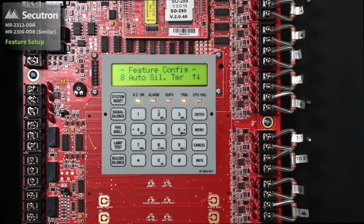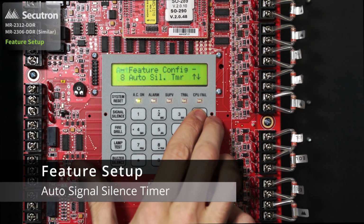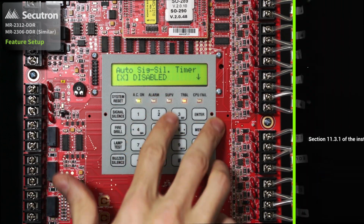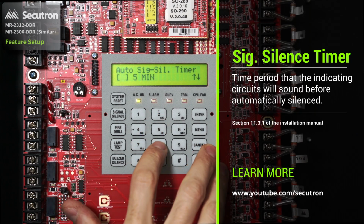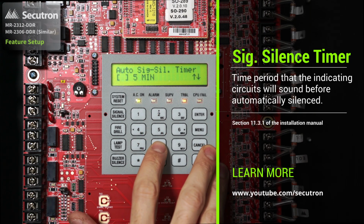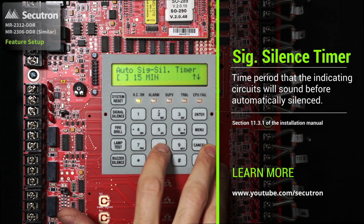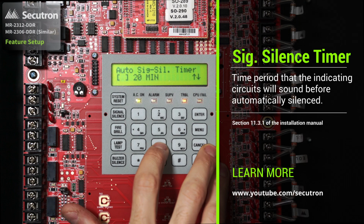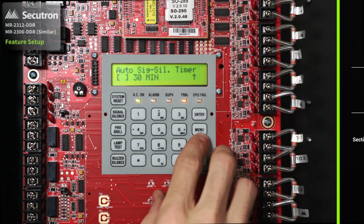The next feature is the auto signal silence timer. By selecting Enter on the auto signal silence timer, we can have it as disabled, or we can scroll through and find the various time segments that we could set this for, whether it's 5 minutes, 10 minutes, 15 minutes, 20 minutes, or 30 minutes. Use this function to determine the time period for which the indicating circuits will sound before they are automatically silenced.